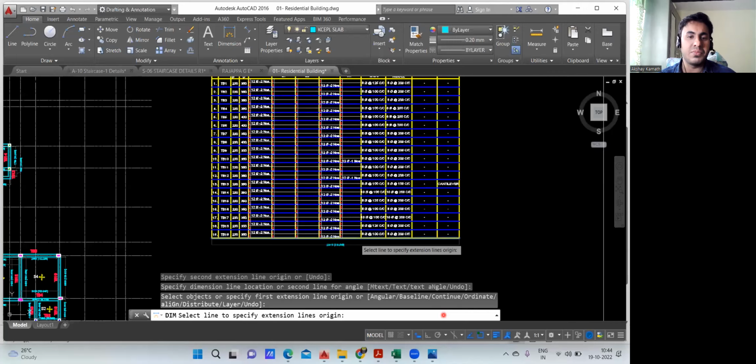You multiply, you get the concrete quantity in the beam. Okay, come here. So I've written only one mid landing beam. Length was 3.4 meter, breadth was 0.2 meter, depth was 0.35. Total quantity will be 3.4 into 0.2 into 0.35, which gives me 0.238, and total quantity will be quantity into number of landing beams, which is 1. So if I add using auto sum, 1.109 plus 0.612 plus 0.535 plus 0.238 will give me 2.494 cubic meter of concrete required. So this is for one single floor. One single floor I have done.